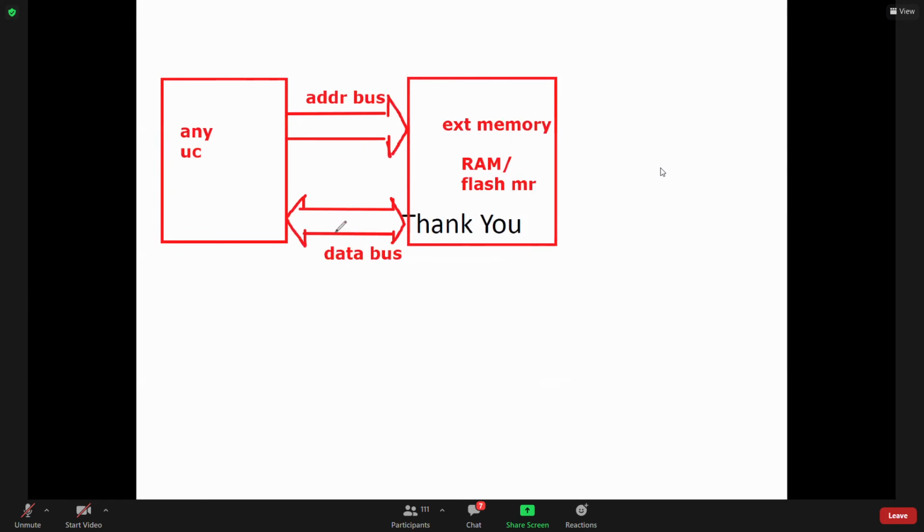And in the case of 8051, the data bus is available on port 0, and the address bus is available on port 0 and port 2. Total 16 address lines are there. It is not possible to have a 16-bit address bus on one port only. To interface external memory, we have to use port 0 and port 2 of 8051.